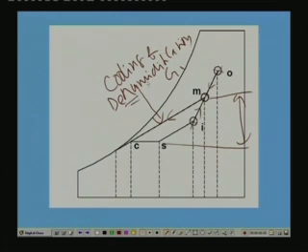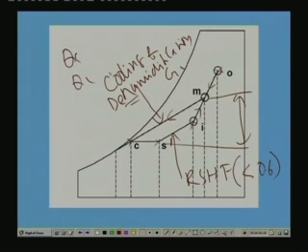So that is achieved in this process, but you find that this point does not lie on the RSHF line. This RSHF will be quite low because of the high latent load, let us say less than 0.6. Since this point does not lie on this line, if you leave air at this condition to the conditioned space, it cannot take the required amount of sensible and latent heat loads. So somehow you have to bring this point onto the room sensible heat factor line.